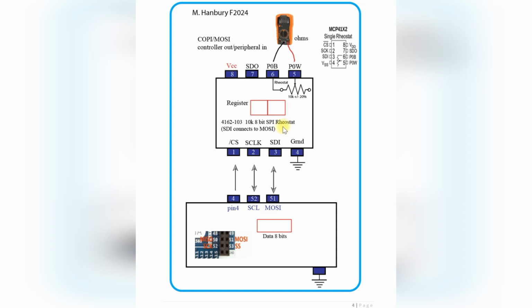So one of the first things that we do is to measure the maximum resistance by setting this register to FF. We're going to be connecting our oscilloscope to 2 pins. Channel A is going to be connected to the serial clock, and channel B is going to be connected to master out, slave in, which connects to the serial data. And then we're measuring the resistance up here.